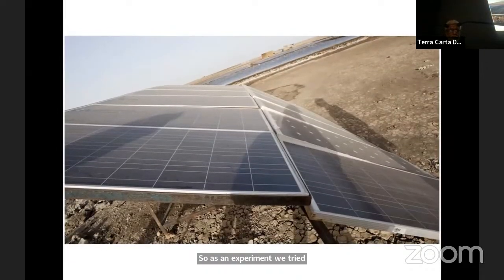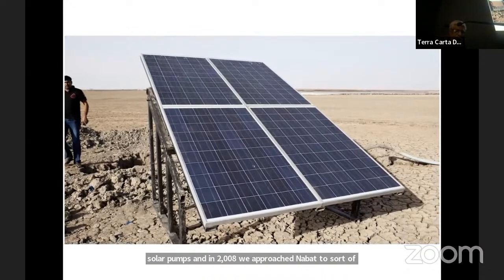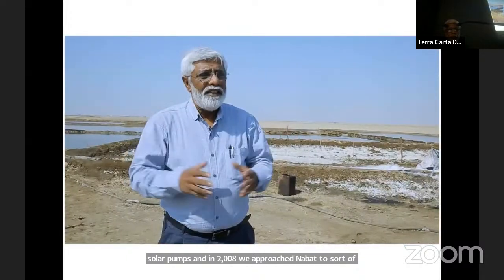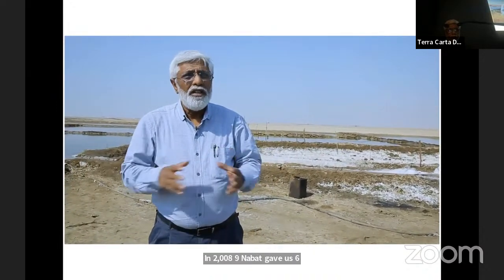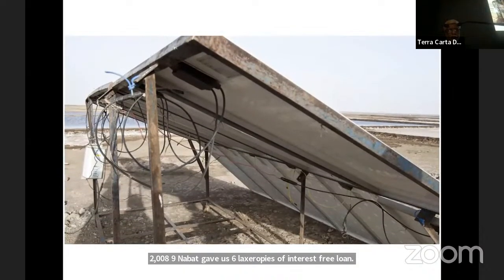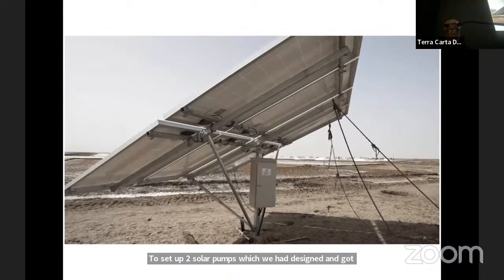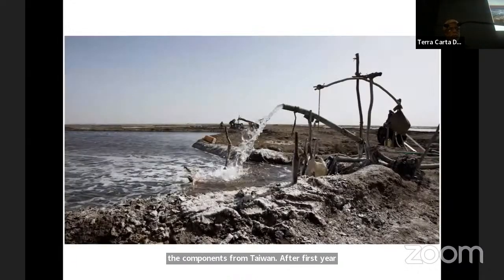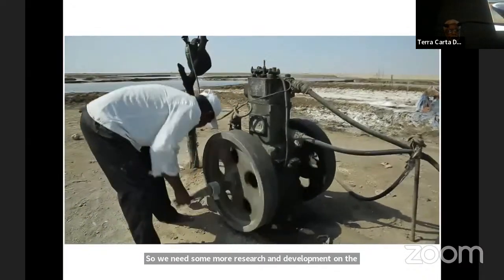And in 2008, we approached NABARD to sort of provide us some assistance so that we can really start looking at exploring this and scaling it up. In 2008-9, NABARD gave us 6 lakhs rupees of interest-free loan to set up 2 solar pumps, which we had designed and got the components from Taiwan. After first year of introduction of the solar pumps, we realized that we are only pumping out 50,000 liters per day. So we did some more research and development on the pumps. Eventually, we designed a pump which could bring out 1 lakh liter per day, which is the requirement of the salt producer.